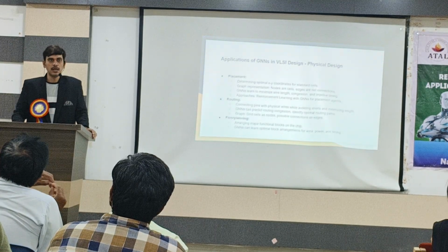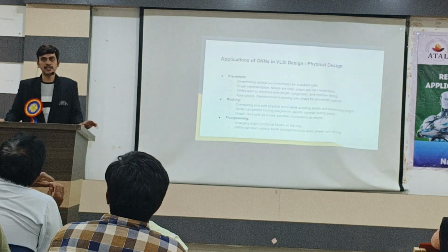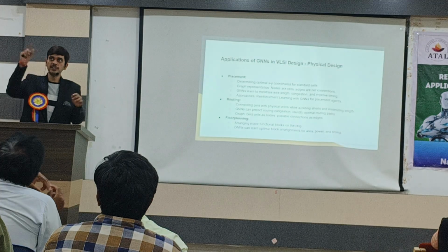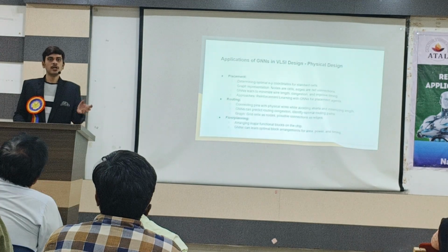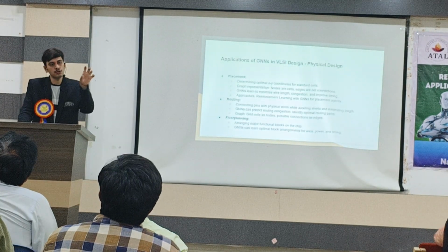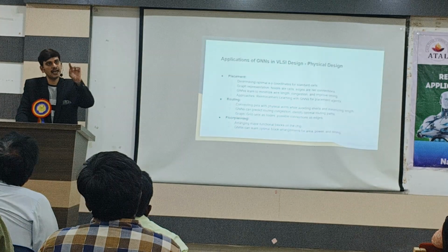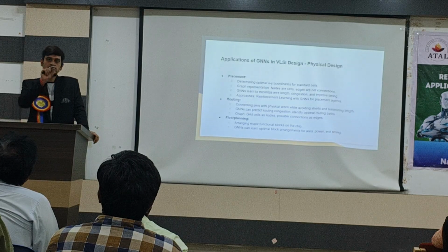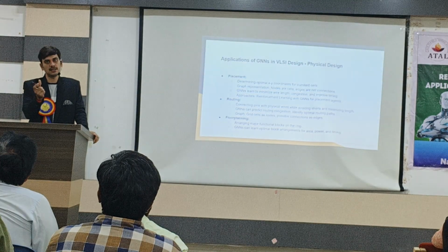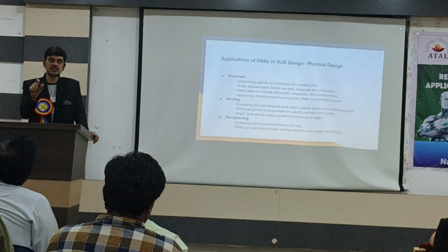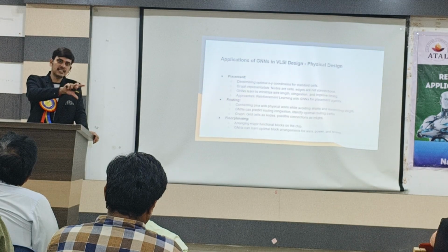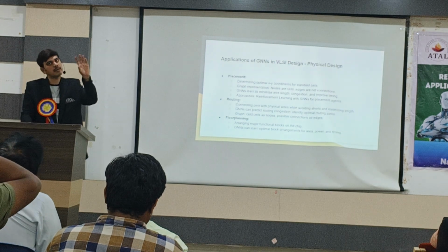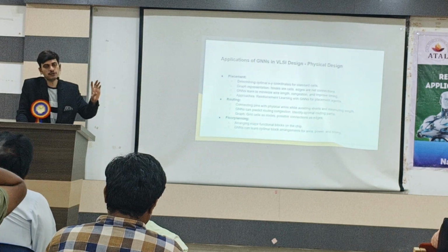For example, I have a 100 ps timing violation, but the data path is fully optimized. You can't do anything at that point of time. What we have to do is check the connections, like to which macros or which channels should be handled. So we can require the PNR to take those cells and we can have a home. We have the concept called home. You can view the coordinates and the cell hierarchies to see at what point you have to place those cells. Those particular cells will sit in a particular place as a group, so that all those cells will be closer and the timing will be met. This is one of the strategies we use.